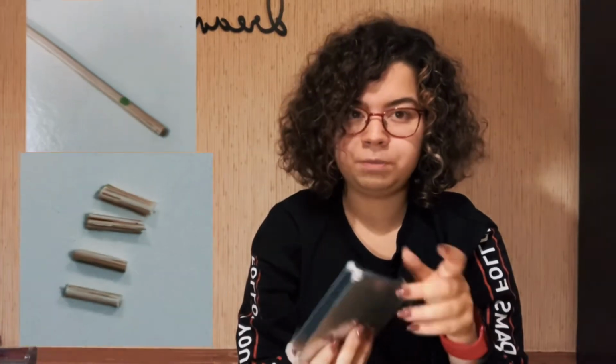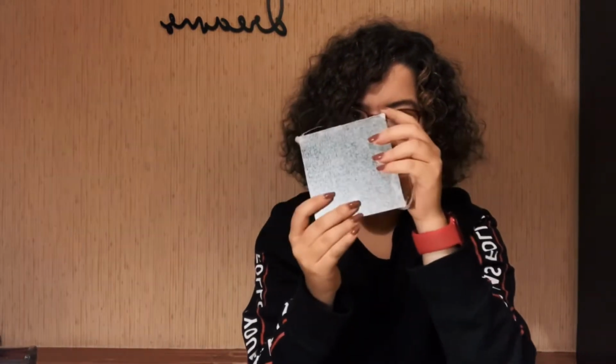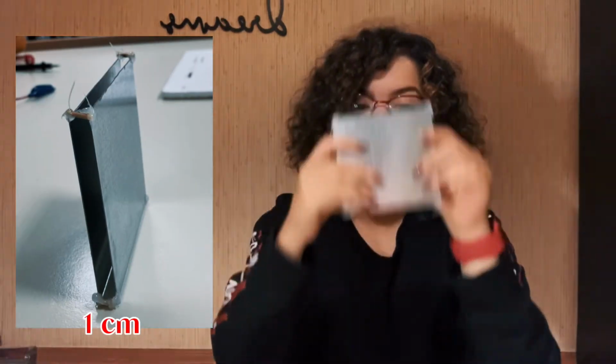In the first part of my experiment, I made a capacitor. I cut 4 pieces with a length of 1 cm from the skewer because I wanted the distance between the plates to be 1 cm. Then using hot glue, I glued the 4 pieces to the corners of the plates to make the distance between the plates equal everywhere and 1 cm.